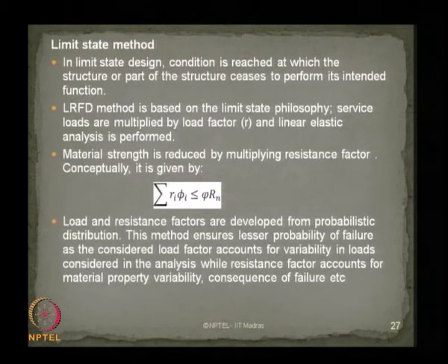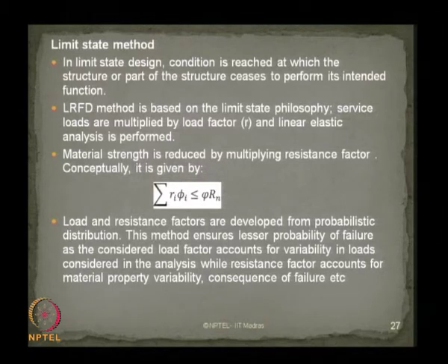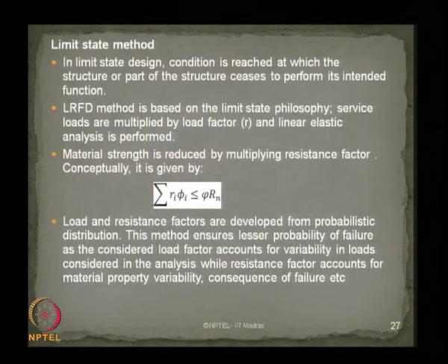Load and resistance factors are developed from probabilistic distributions. This method ensures a lesser probability of failure. The load factor accounts for variability in the loads considered in the analysis, while the resistance factor accounts for material property variability, consequence of failure, etc.